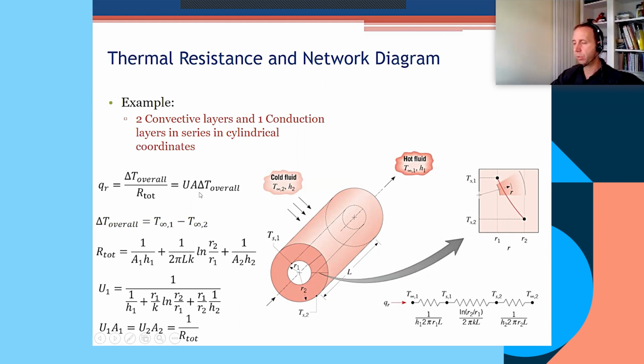And there's a definition of the U value, which is quite similar to the resistance, but it's the inverse of it, and the U value doesn't involve the area. So I'll discuss all that later on. But what's important is that if you rely on the U value to do your calculation, remember that it shouldn't be defined separately from the area when the area changes. So we'll come back to this notation later on. And that's the end of this first part of chapter 3.